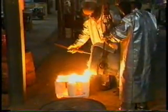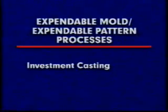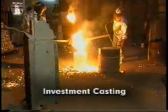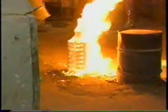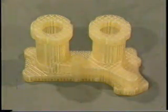Expendable mold, expendable pattern processes include investment casting and evaporative foam casting. Investment casting is a precision process using primarily ceramic shell molds. Investment casting is also known as the lost wax process because wax, a principal pattern material, is consumed during the mold-making process. Consumable plastic patterns are also used.